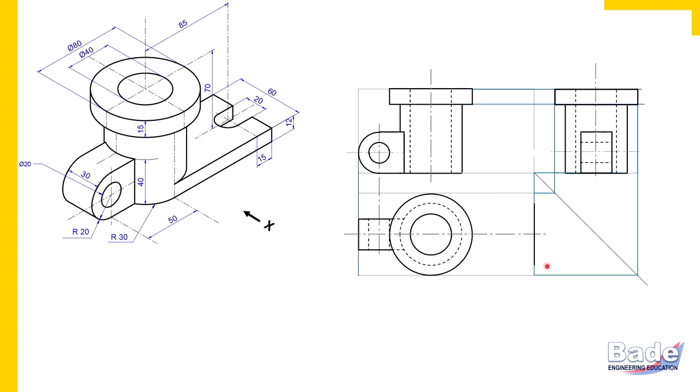It is 60 millimeters long. So I measured here 60 millimeters. Check this dark continuous line. And this cylinder edge under the top cylindrical plate, these edges, watch here, this edge and the corresponding edge on the back side. So this edge on the front side and the corresponding edge on the back side, under this circle, we have shown dotted. Like the U-shaped block, this plate also comes in contact with the cylindrical surface. It is attached to the cylindrical surface, this cylinder. So let's show that attachment properly.